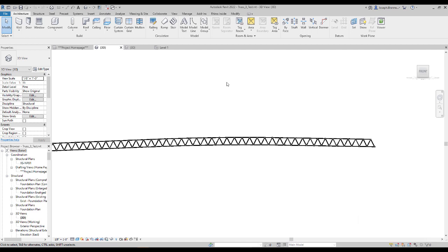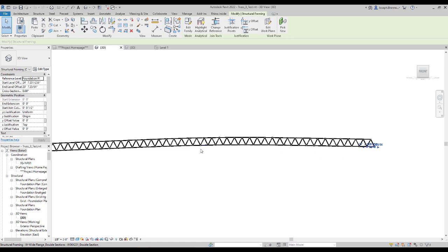All right. So the first thing I want to do, right here in Revit, is take a look at what we can do specifically with quantities and volumes. If I select any one of these members, I can select multiple at a time, but in this case, I'm just looking at a lower chord. And I can get different information from this just because we're in Revit and we have a Revit object now.